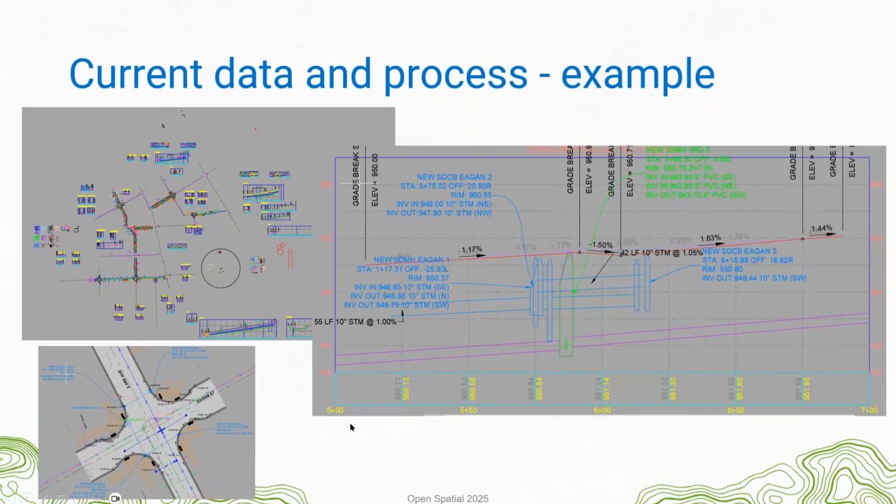If it's a Civil 3D drawing, this stuff is still there, but it's interesting because we're actually dealing with a full workflow, and often the design's fully 3D. A lot of stuff gets done there, but it goes out to construction, and often the drawings are flattened, so actually the as-built becomes not the Civil 3D drawing per se, but a flattened CAD drawing, which still needs all of those attributes, and they will have ways of pulling those out.